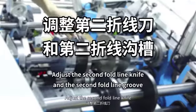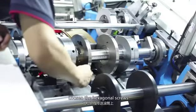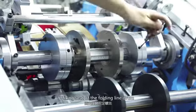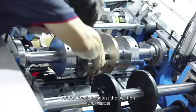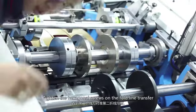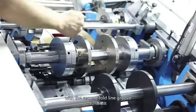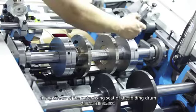Adjust the second fold line knife and the second fold line groove. Loosen the hexagonal screws on the folding line transfer drum and loosen the fixing screws on the outside fixing seat of the folding line drum. The second folding knife can be rotated freely to adjust the position. Tighten the hexagonal screws on the folding line transfer roller until the second fold line knife is aligned with the second fold line groove. Tighten the fixing screws of the outer fixing seat of the folding drum.